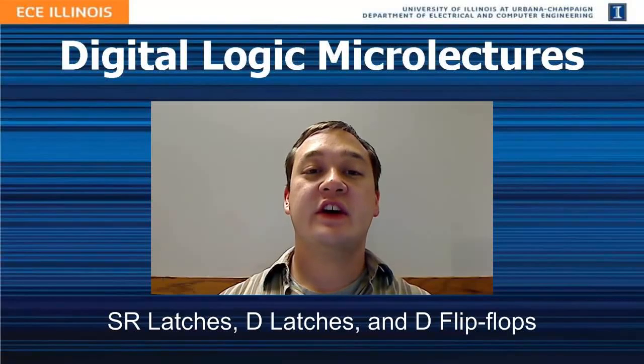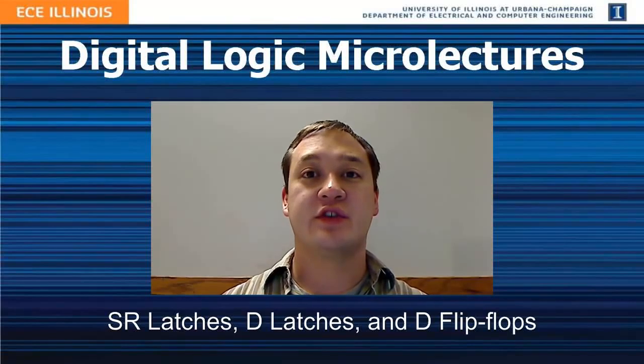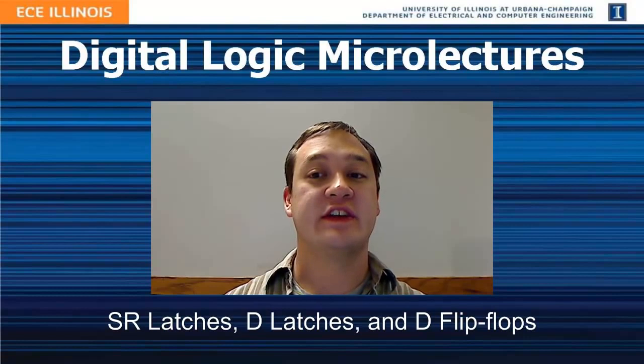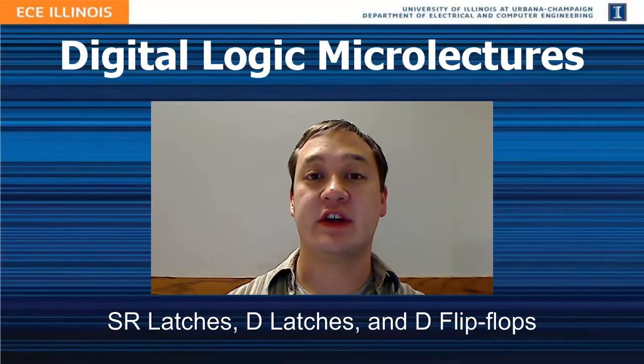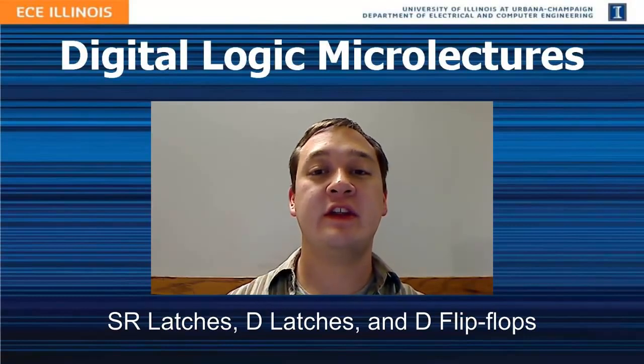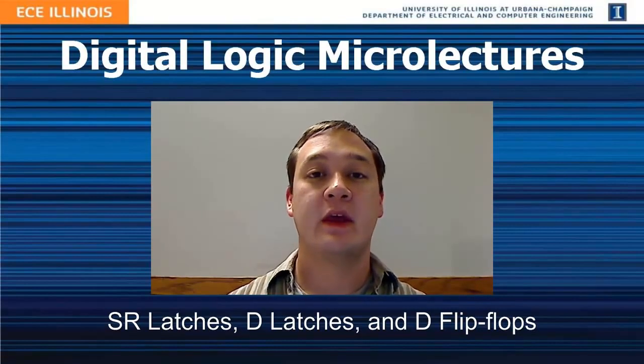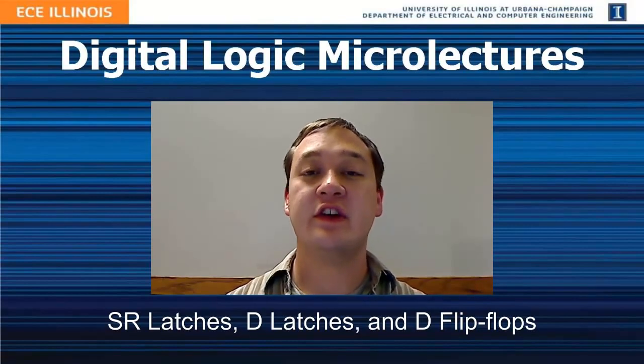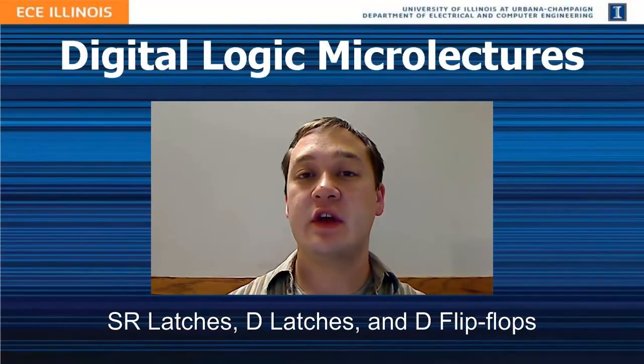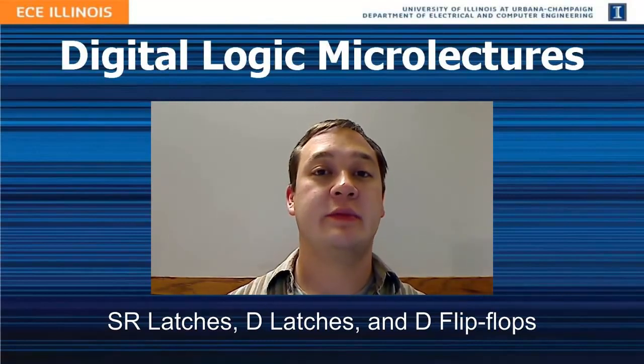In this lecture, we discuss how we create circuits that can store state. Circuits that store state are called sequential circuits and are created by feeding the outputs of the circuit back in as inputs. In this lecture, we introduce the SR latch and later the D latch, which both store 1 bit of state.